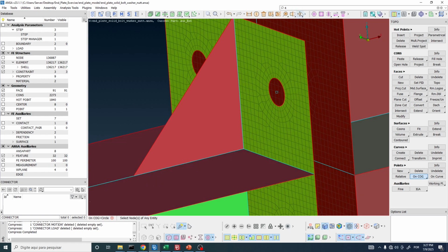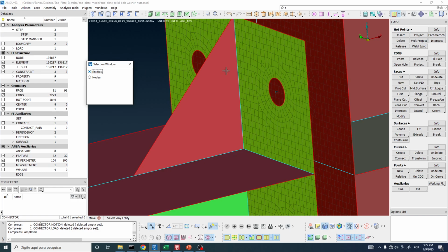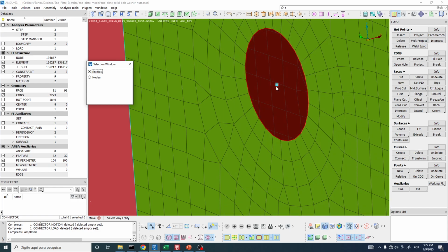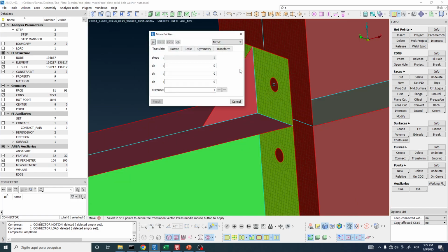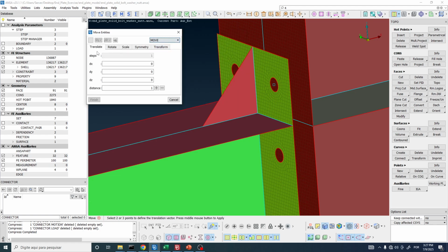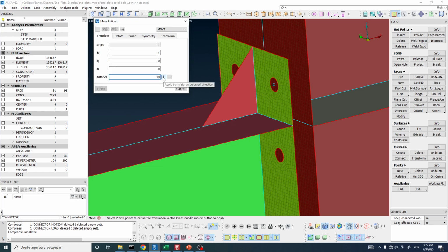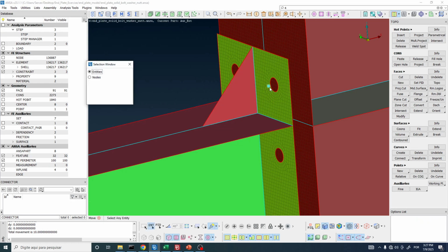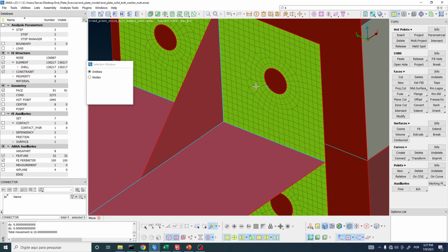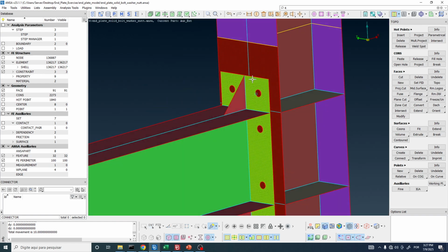So let's do this. Let's use the transform tool that you can find here, or maybe here. Okay, transform and move. I want to select entities because a point is a kind of entity. Zoom in, select this point, middle mouse button, and then move, translate, tab, negative x direction, 10. Guys, I'm going to start being a little faster here, okay? Because these are tools that I have already used before. Plus, finish. Now we have the point here. Escape to deactivate the tool.